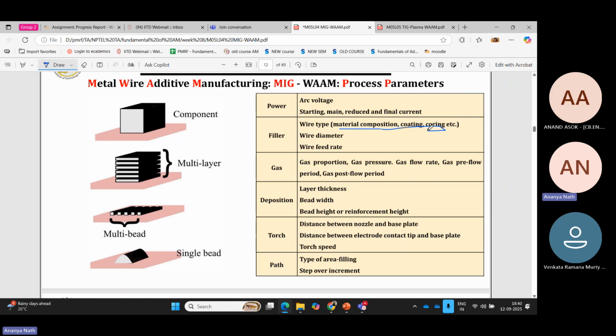Gas has another job: the fed gas also maintains the melt pool shape. The melt pool shape is something from which you get the final bead geometry and the final bead property. If your melt pool shape is distorted, you are going to get some porosity, cracks and residual stress as well. So gas is very important.